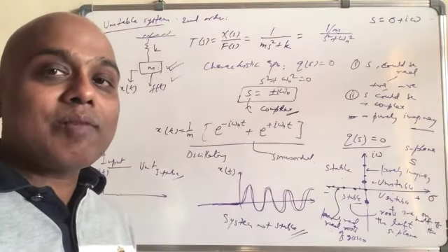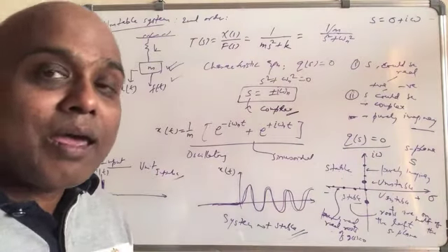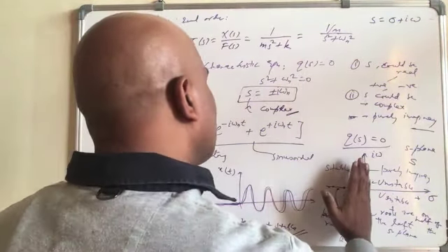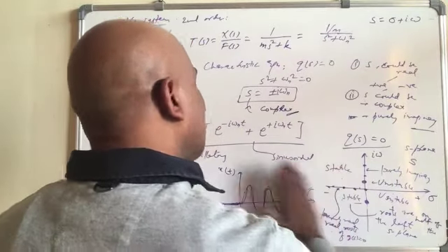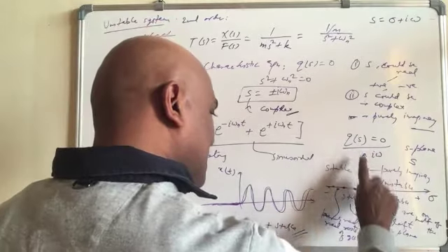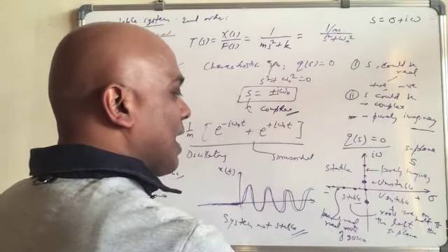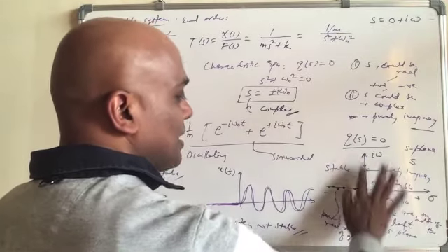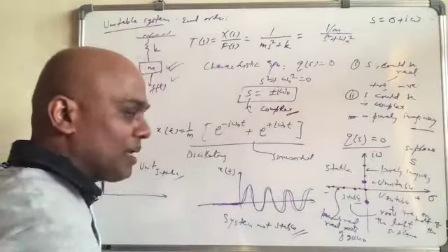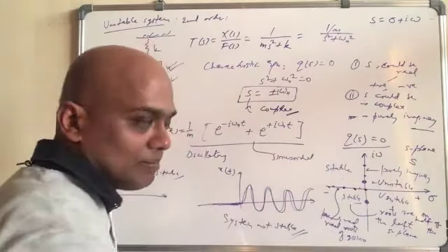And from there we can find out whether the system will be stable or not. The system is stable when the roots are on the left hand side of the S-plane, and it's unstable if they are on the vertical imaginary line, as well as on the right side of the S-plane. So for stability, we want the roots to be on the left side.